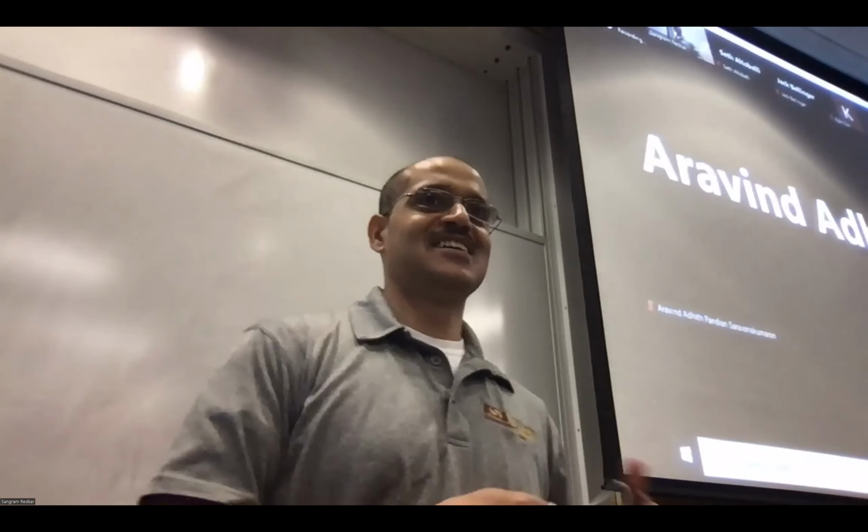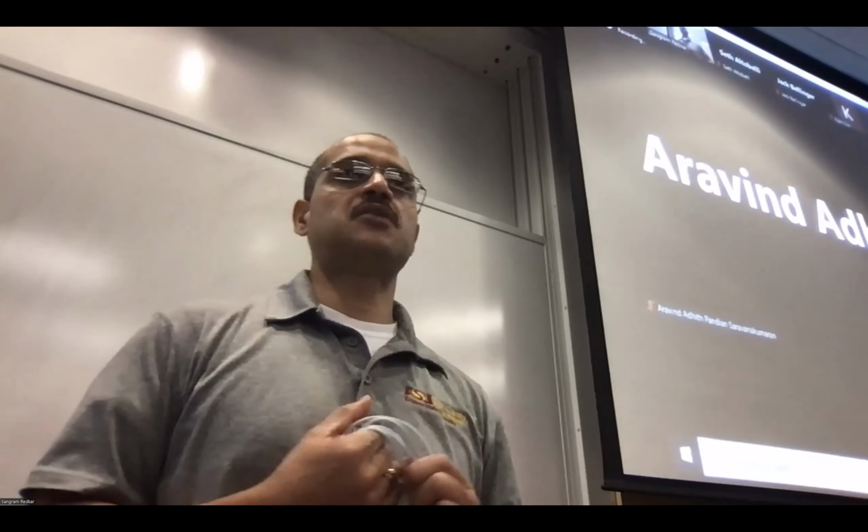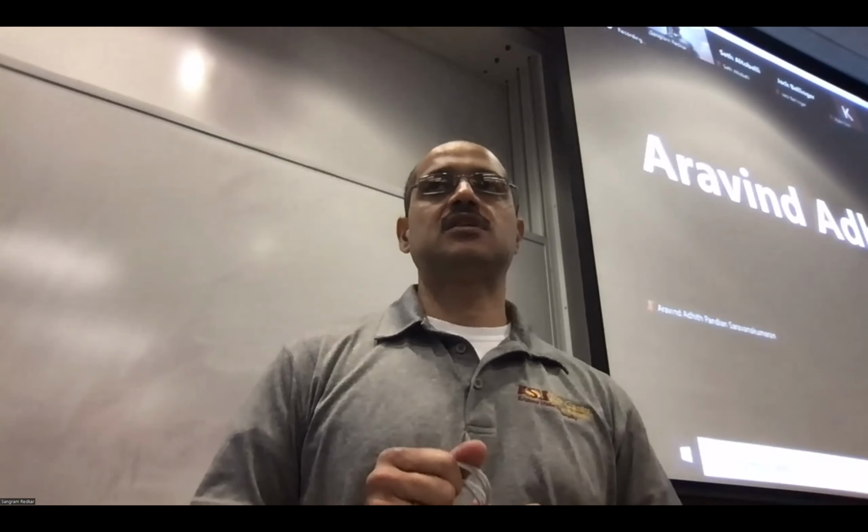Hover control assignment is due next week, next Tuesday. For the first time I finished it on time. Oh, you got hover control working? It actually hovers? No, I didn't try it because one of the motors is not working. I tried it like this and it was working, but one of the motors is not working. Hover control will not work just based on P control. You will have to add the D. Without that, it will not work.